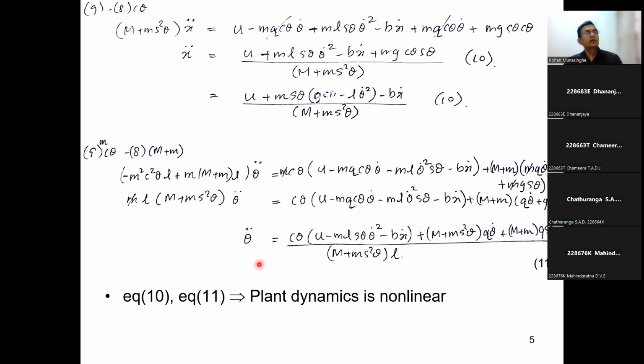So there you are. Now you have a complicated, nonlinear equation, but the good thing again is that you can program this equation and update theta double dot. Once you know the acceleration of the angle, you can calculate the angular velocity and the position, the angle itself. Then you can simulate the whole motion, not only the cart, but also the pendulum in MATLAB.